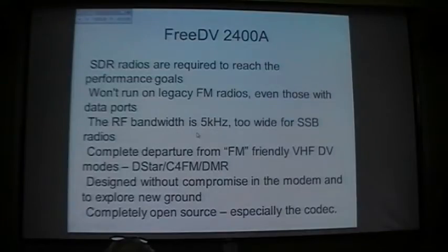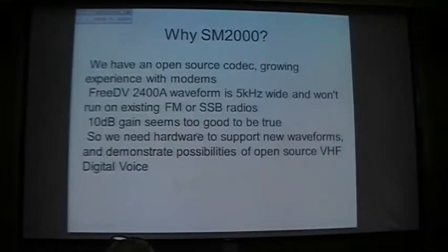It's a complete departure from FM-friendly VHF, UHF digital voice that everyone else is doing at the moment. And that's on purpose. The current FM demodulator architecture, as I've illustrated, causes big performance drops, and we can do a lot better than that. So it's designed without compromise in the mode and the radio to explore new ground, rather than saying, oh, we've got a bunch of old radios, how can we reuse them? So no apologies for that. And it's completely open source, including the codec. No lockdown, no licenses, quite free to experiment.